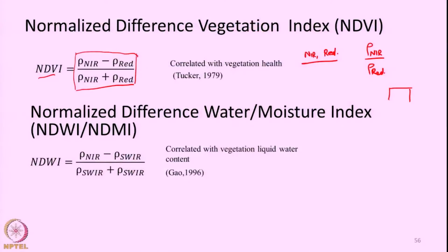that is let us say one single pixel is here, some feature is there, let us say some portion of the pixel is covered by cloud. Okay, so this is pixel number 1, there is another pixel 2, some other pixel. So, a single cloud is kind of distributed across 4 different pixels. Due to the presence of cloud here, the reflectance between land surface and the cloud will be totally different, and for such mixed pixels the NDVI value will be either negative or in the range of 0 to 0.2 on the positive side.